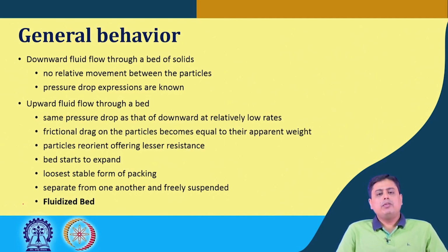Okay, so we will go into this phenomena now in deeper state. So now you can understand that this fluid state can be either liquid phase or the gas phase. Now what would be the difference between the two systems? Say you have a liquid-solid system and a gas-solid system. So two states of fluidization can happen: gas-solid fluidization and liquid-solid fluidization. Okay, and what would be the difference between these two?